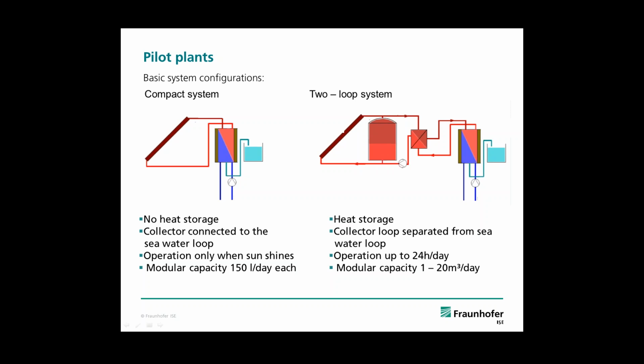You can also see, as I mentioned earlier, that at high temperatures, on the left-hand side of the graph, the flux is much higher than in the low temperature zones of the module. But with respect to heat transfer, it's quite important to have huge surfaces, and that's also the trade-off that you have to be aware of if you want to optimize the membrane distillation process.